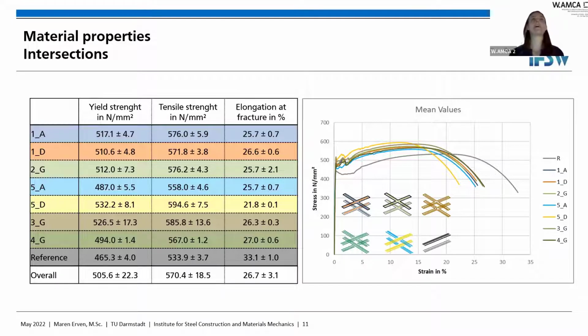That's also one point one can investigate: how the cooling and the cooling time between the layers influence the behavior, and also the type of cooling, because we also used air pressure, and air pressure with water inside. We tested that, and the behavior was actually the same, because the weld is so hot that it just takes out the energy, and then the hydrogen is away, and you can weld on it again. But I don't have any results yet.